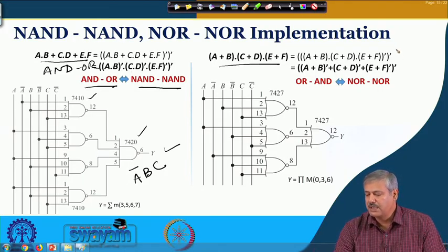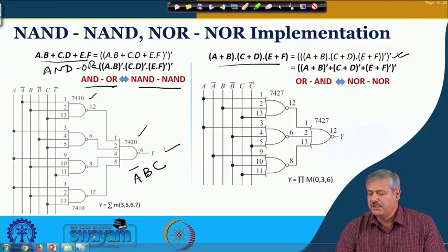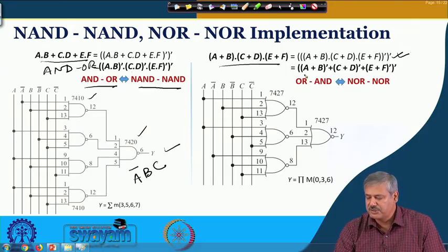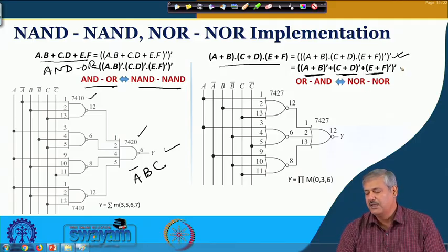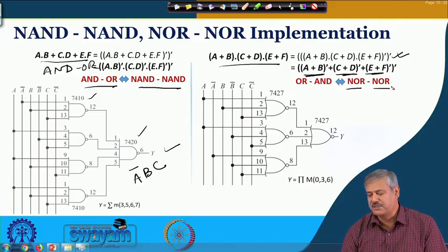In that case you take the double complement, and then use De Morgan's theorem. So, this is one NOR gate, this is another NOR gate, this is another NOR gate, and finally a 3 input NOR gate combines all of them and you get a NOR level representation. Similarly, for this particular example we have one NOR bank followed by another final NOR output stage, and we can get the same result.